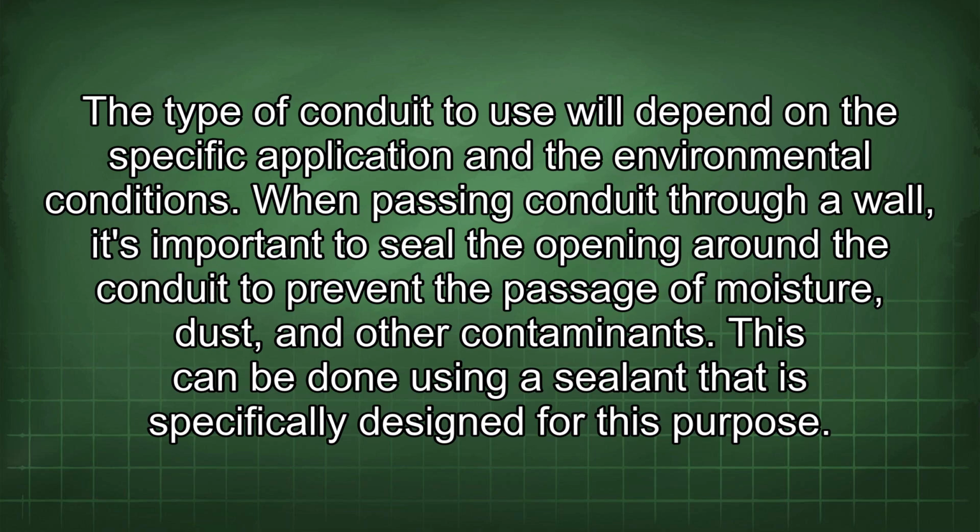When passing conduit through a wall, it's important to seal the opening around the conduit to prevent the passage of moisture, dust, and other contaminants. This can be done using a sealant that is specifically designed for this purpose.